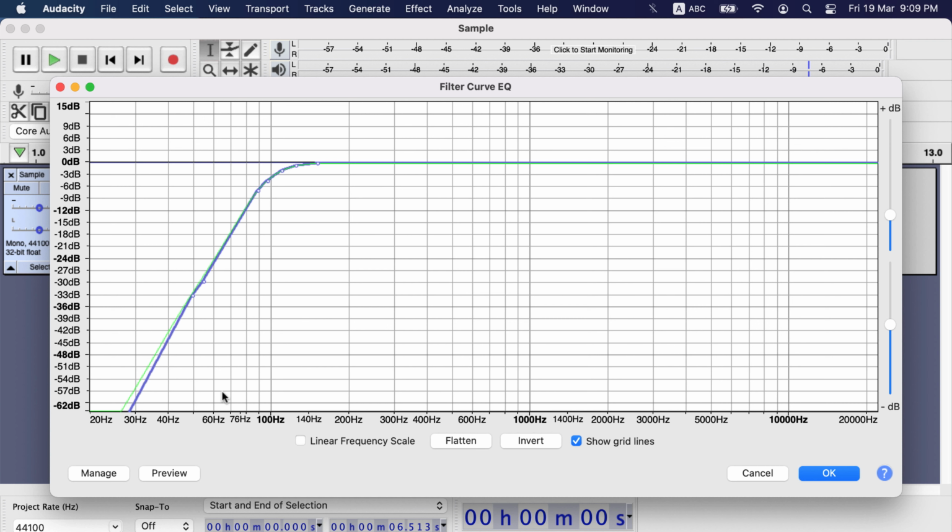Worst thing is certain noise, like something heavy falling on the floor, produces frequency in that range. So blindly applying bass boost increases those noises, if you have any. 100 Hz rumble cuts out those noises.